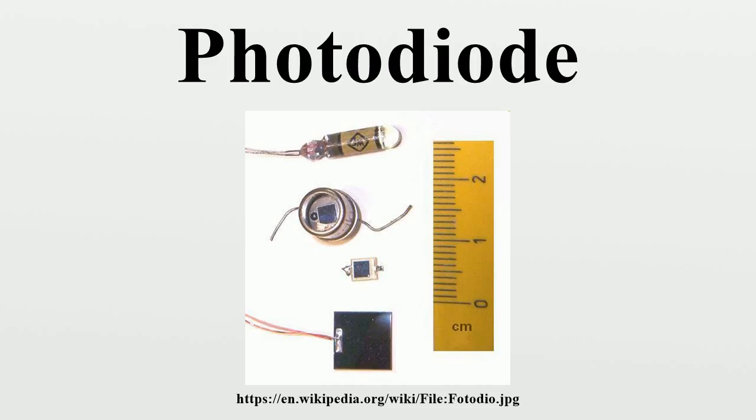Response time. A photon absorbed by the semiconducting material will generate an electron-hole pair which will in turn start moving in the material, under the effect of the electric field, and thus generate a current. The finite duration of this current is known as the transit time spread and can be evaluated by using Ramo's theorem. One can also show with this theorem that the total charge generated in the external circuit is e and not 2e as might seem by the presence of the two carriers. Indeed, the integral of the current due to both electron and hole over time must be equal to e.